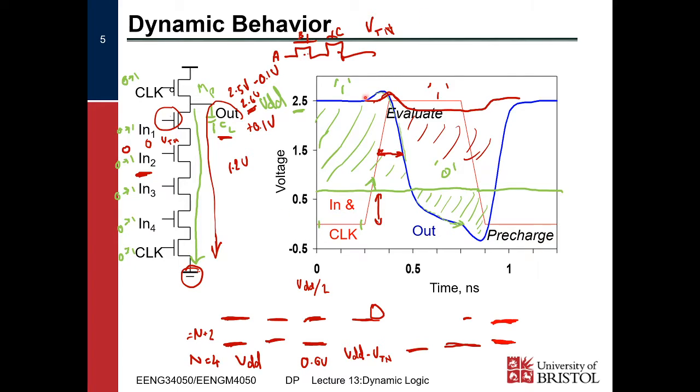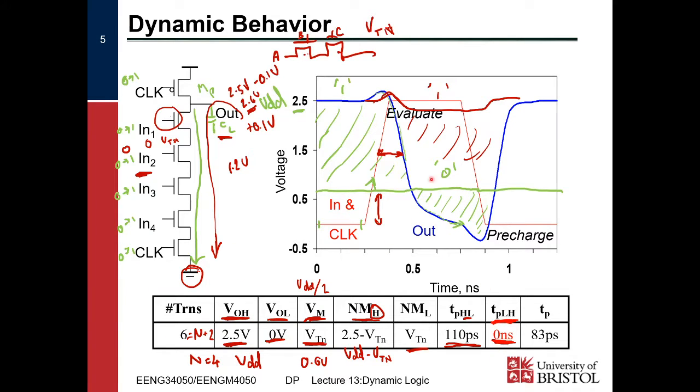We saw how the low to high time is 0, due to the fact that our input always starts off high, whereas our high to low time is our key critical path. It's the propagation delay of our gate, and it's what we need to design for. But because this is all dealing with NMOSes, and NMOSes tend to be...